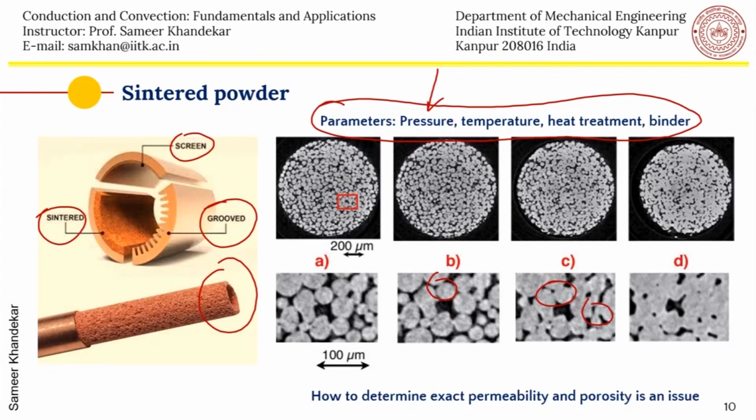Of course, how to determine it is always an issue, as I said, for such type of complex wicks, wherein the porosity and permeability typically have to be found out either by some electron microscopy or some microscopy, or better still by some porometer, and conducting experiments to fit Darcy's law and try to get the permeability. So we will talk about it mathematically in the next slide.